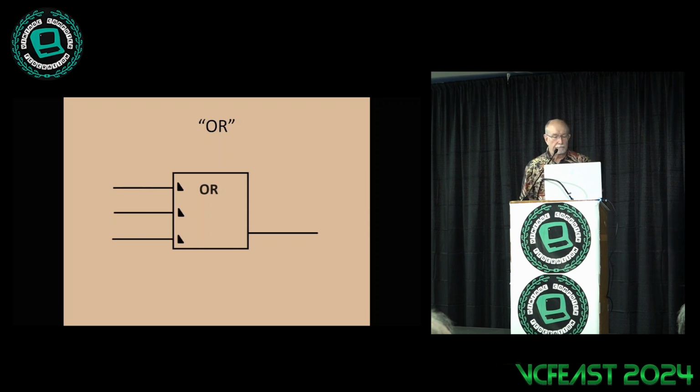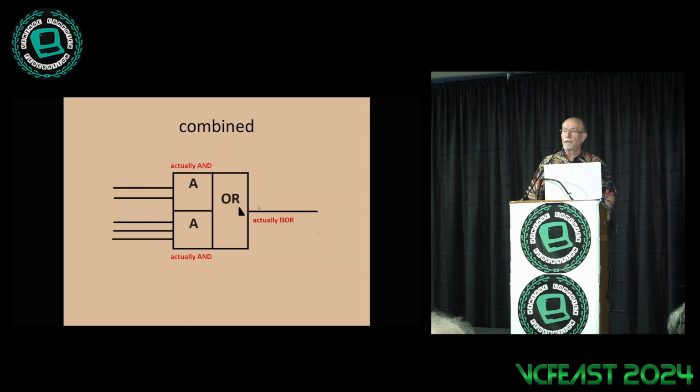Here's another one, the OR gate. You see this a lot in SLT as well. Now you notice that the inputs are inverted and the output's not. So if any of the inputs is low, then it's true and you get a 1 on the output. Exact same truth table. It's a NAND again. So they have 2 different ways of drawing a NAND gate, none of which look like anything you're used to. So still not too bad. Once you figure out the translation, you know how to deal with this.